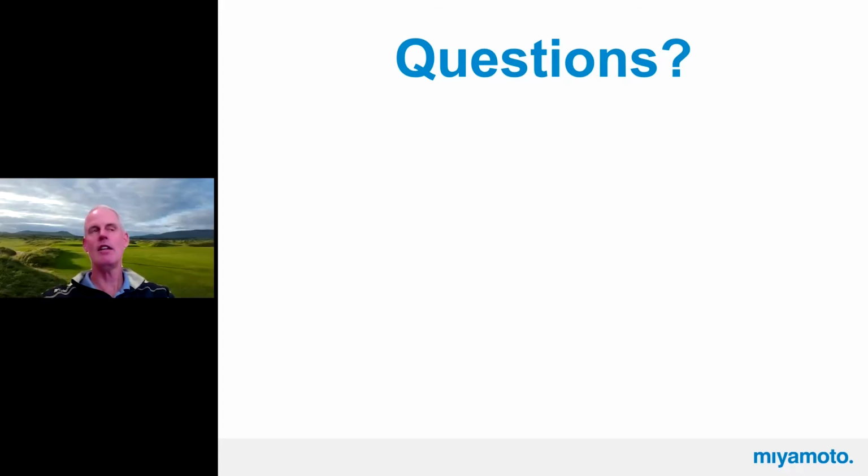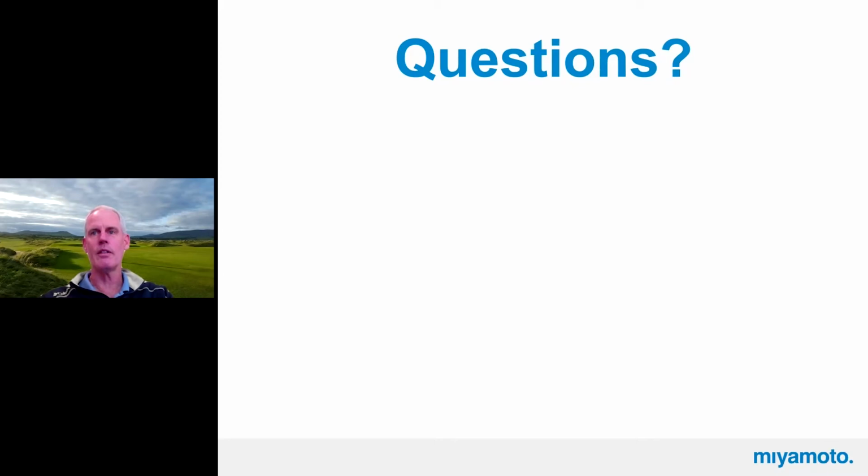Hey Jeff, this is Pete. It's been a while since I've done some of the elevator equipment room, but there's some very stringent deflection criteria for elevator machines. It's like L over 1666 is in my head for elevator equipment. Yes, that's true. That's in the ASME, I learned last night. So you need to pay attention to that too. I didn't really get too into that. And also, we don't see that many traction elevators. Correct. But you're right, it's rather stringent criteria.